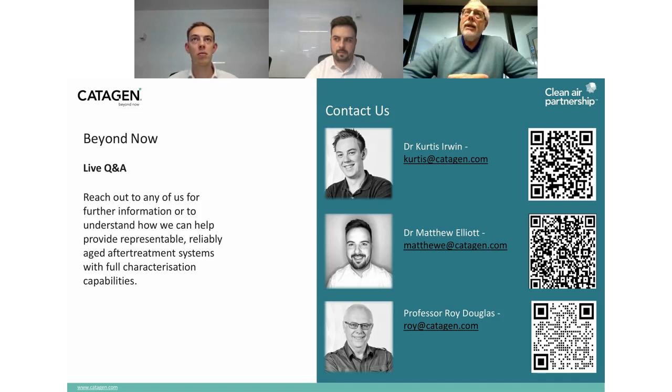So in that case, the light off isn't going to be particularly helpful. We've been thinking for a long time how to evaluate post light off, because we do notice that in a heavily aged catalyst you never reach 100% even after light off. And so we feel that this will be very helpful